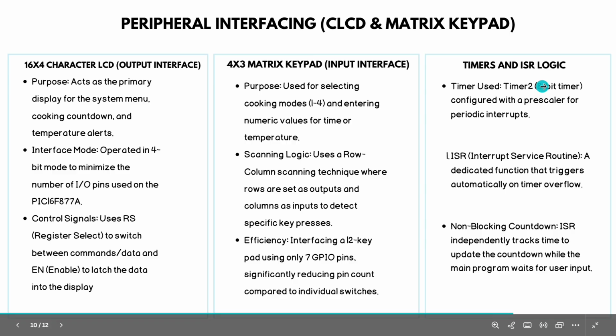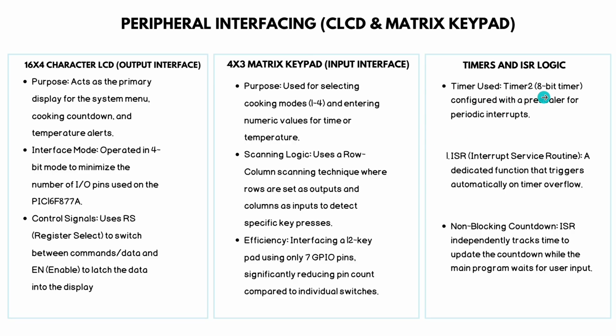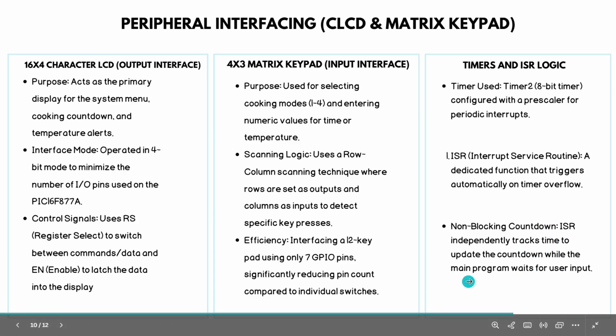Timers and ISR logic. The timer is used as an 8-bit timer configured with a prescaler for periodic interrupts. The second one is the ISR, known as the interrupt service routine, a dedicated function that triggers automatically on timer overflow. The third one was non-blocking countdown. The ISR independently tracks time and updates the countdown while the main program waits for user input.